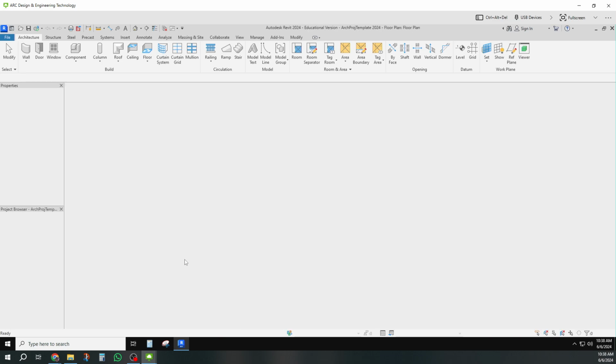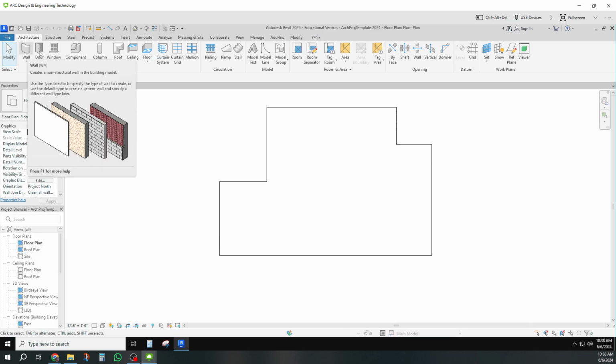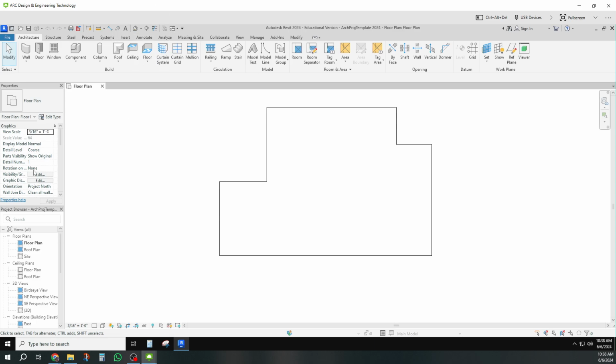You're going to see that Revit always starts up with different ribbons in the top. We're going to live in this architecture one and in this annotate one. But there's also the properties box. That's very important. Whenever you click on anything, it's got properties, even just being in this view. And these views here, these are like viewports. We can always touch the model in the viewport, but that's what it's like. And it's got a scale, and it's got a place where it shows up, all sorts of things. They've all been set up.